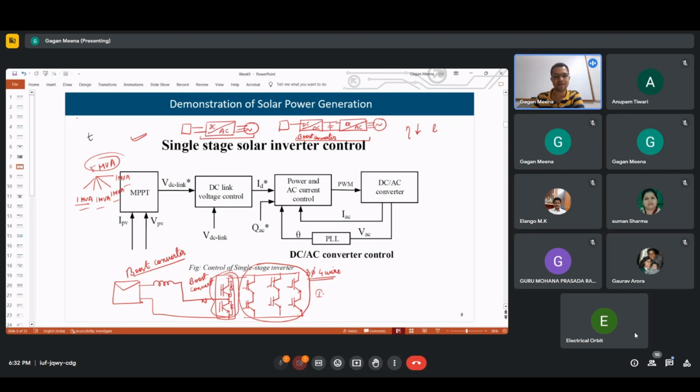Based upon these three modes, whether the rotor will supply or consume power is determined. If the rotor is operating at sub-synchronous speed, the rotor will take power from the grid and the stator will feed power.